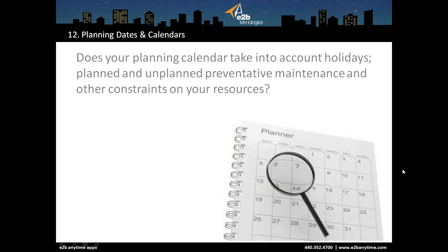If you have holidays and you're not working, if you don't work on a weekend, you need to be able to set that information up so that your MRP or your DRP plan knows that you're not operating in a 24/7 environment. Preventative maintenance, if you're manufacturing: I plan to do maintenance for a day on a particular machine or work center. I can't physically do anything on that machine during that day, so I need to really back that out of the lead time calculations.